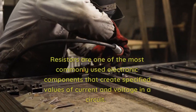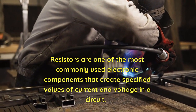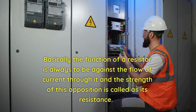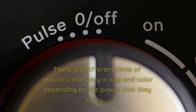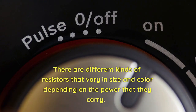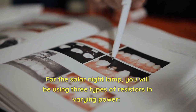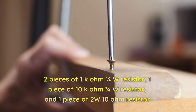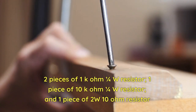Resistors. Resistors are one of the most commonly used electronic components that create specified values of current and voltage in a circuit. Basically, the function of a resistor is always to oppose the flow of current through it, and the strength of this opposition is called its resistance. There are different kinds of resistors that vary in size and color depending on the power that they carry. For the solar night lamp, you will be using 3 types of resistors in varying power: 2 pieces of 1 k ohm 1/4 W resistor, 1 piece of 10 k ohm 1/4 W resistor, and 1 piece of 2 W 10 ohm resistor.